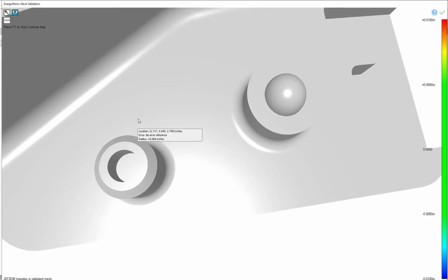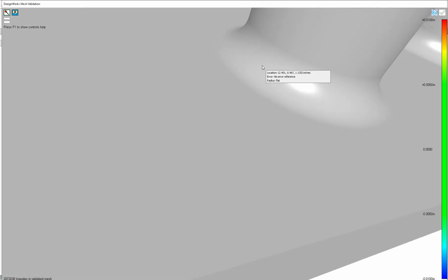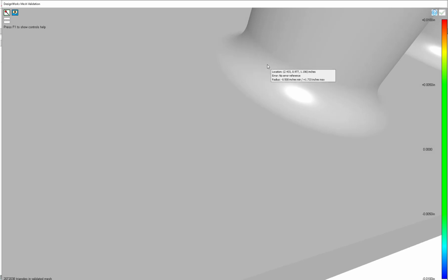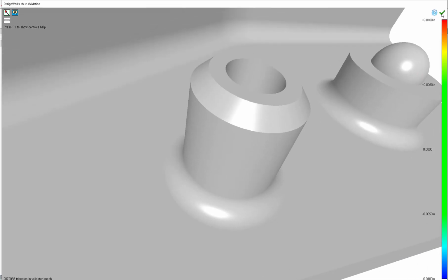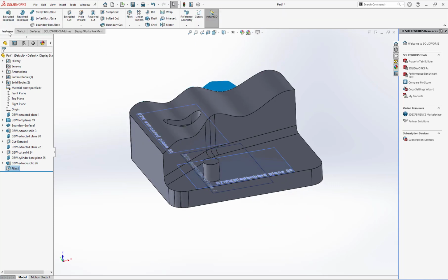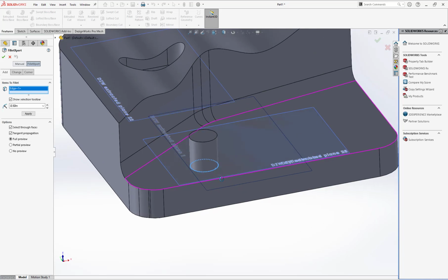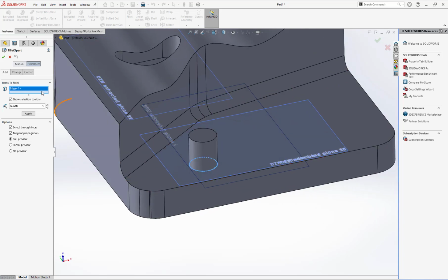And again, sometimes you do need to zoom in. It's a 468. So it's probably going to be about a ½ inch. There you go. We'll zoom in close. ½ inch radius. You can close it. So now, again, you can go with your SOLIDWORKS tools, feature, go into your fillet, 0.5, select the feature just like you do normally. In this case, I could say edge or base or whatever I want.